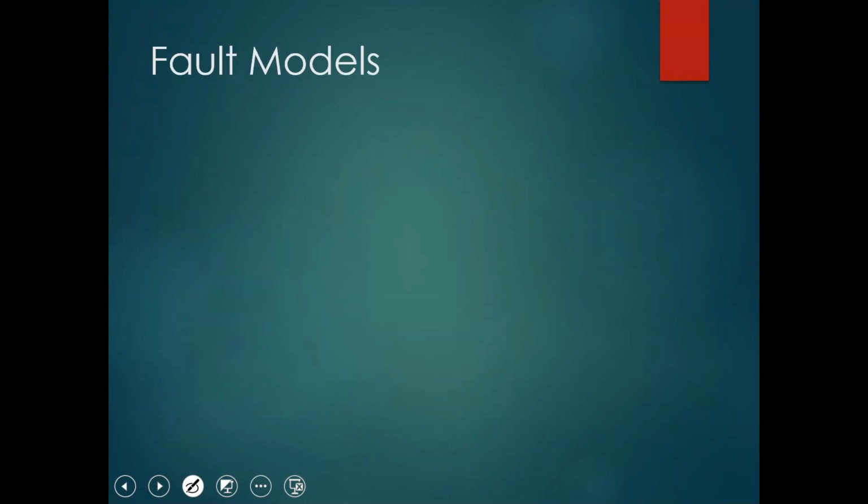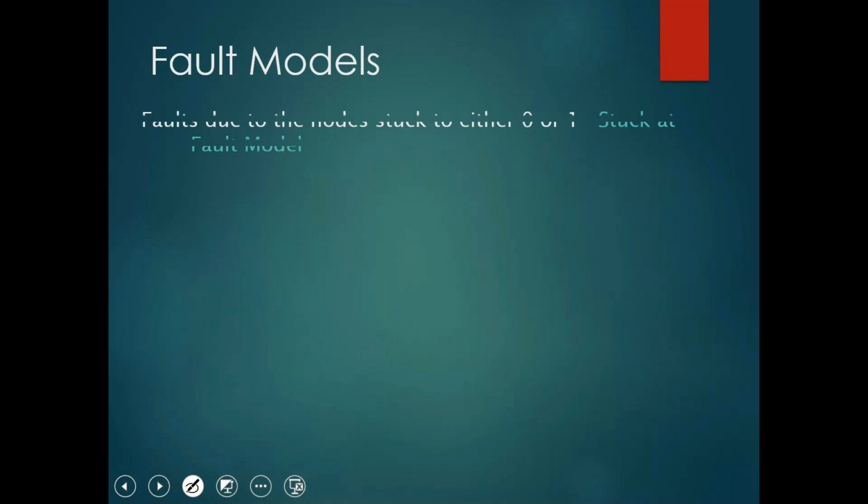So how do you categorize the defects? Now you understood there is a break connection or there is a short connection. How is your software going to understand that? The vector or the test pattern that you write and give to the testing team, how do they classify and tell there is a manufacturing defect where there is a short connection? So we categorize the defects into fault models.